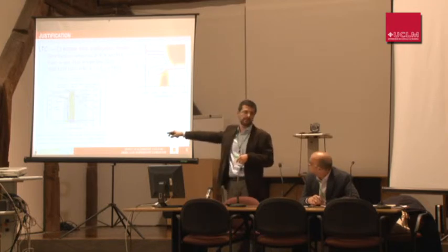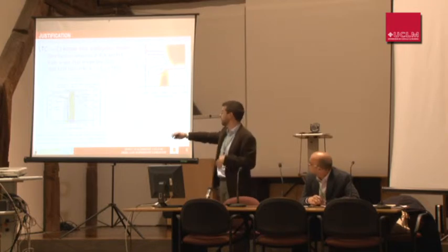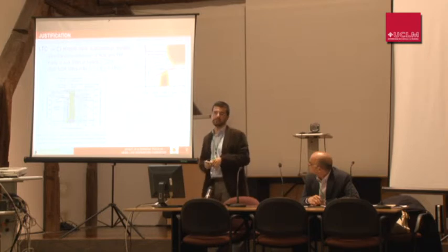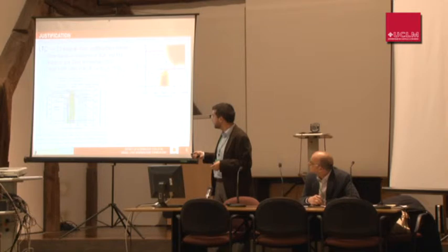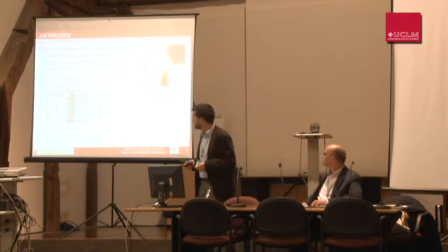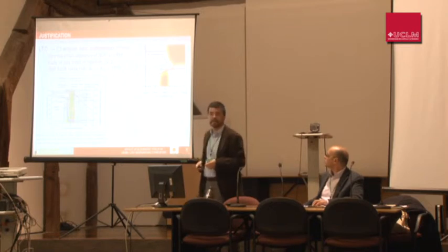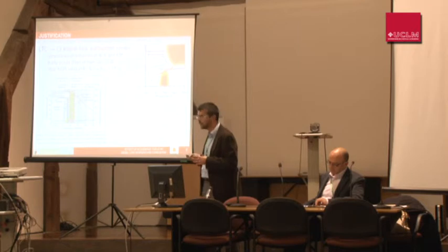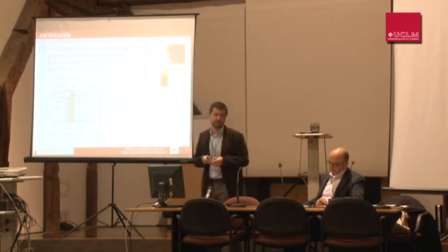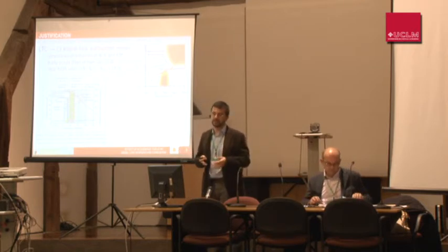This graph comes from a really good paper from Desantes et al. that tries to explain a phenomenological model. We have to take a look at the green line and the blue line. As we can see, the green line is the heat release rate, and the heat release rate begins after injection ends. So that's a highly premixed process.